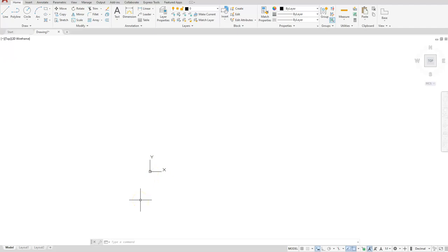In order to tell AutoCAD that I want to use the absolute method, I have to do something first, and that's turn off the dynamic input. The dynamic input is controlled by the function key F12, and you can see that if I click that, nothing really happens on your screen, but when I start typing something in, you will see that it comes up on my command line here at the bottom.